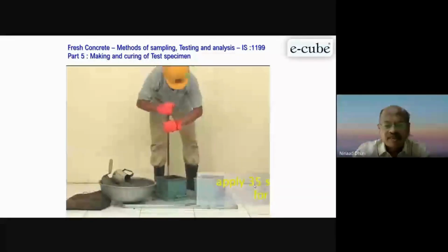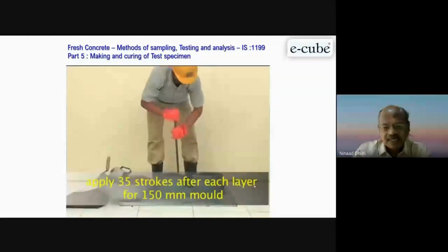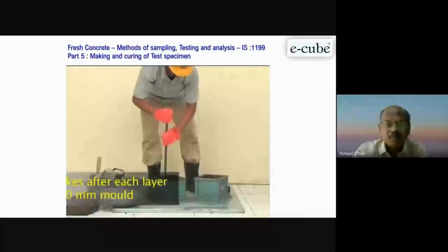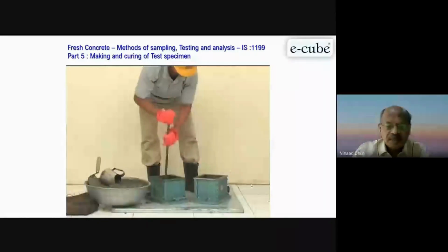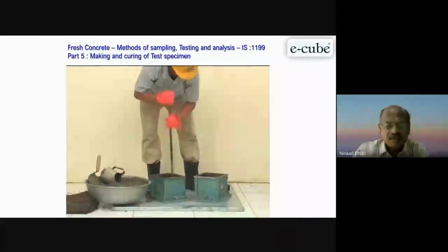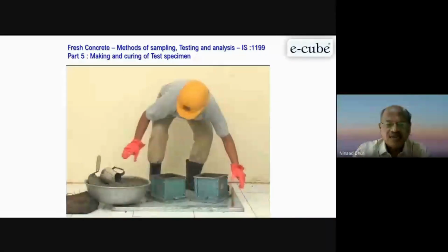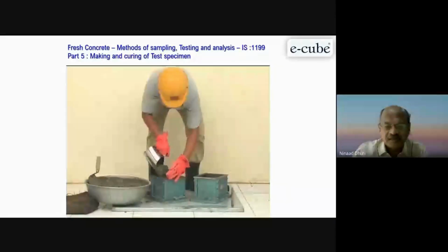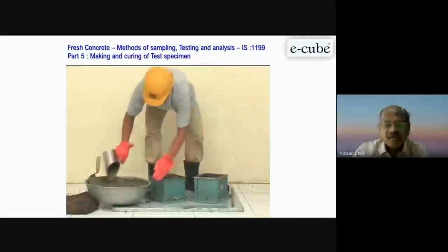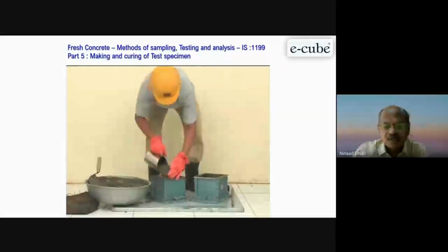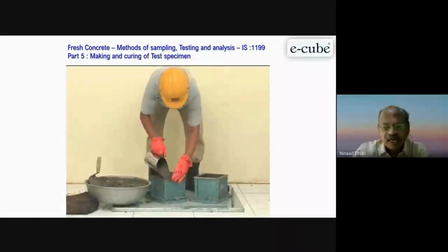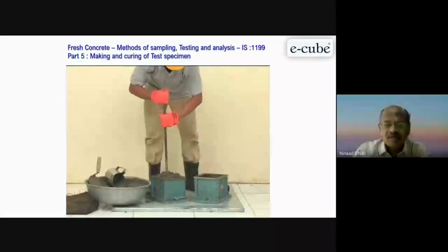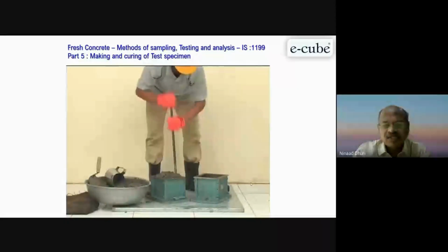It looks like a very simple exercise, and at site generally we don't take care of this. I think we have to train a proper technician to prepare these molds, because all the test results of your specimens or your structure depend on these cubes only. So we have to take care of how the molds are properly prepared, demolded and cured. Otherwise, you'll have a lot of issues and doubt about the concrete that has gone into the structure.